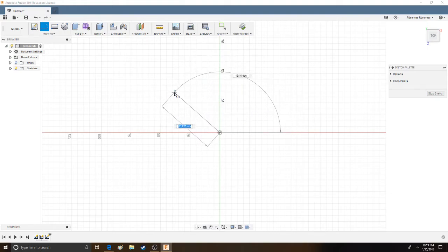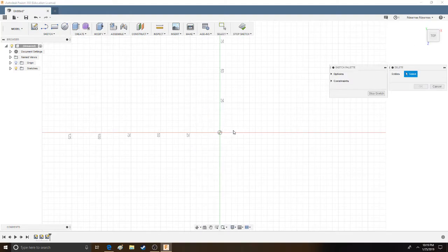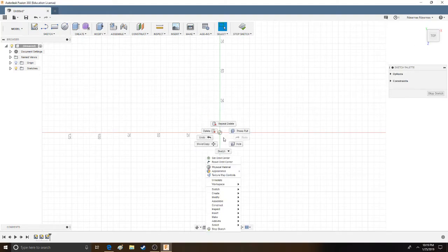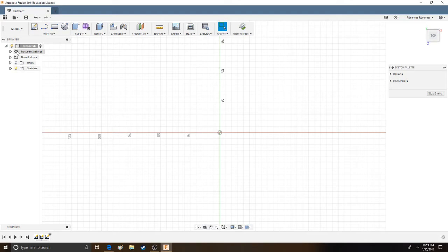So during a sketch, you get this really nice looking grid. So using this grid, we're going to just be going up two sets of 25 millimeters. You can also change if you want. Let me cancel this. Right button click, delete. You can instantly go to that. Right button click has a bunch of different menus, but we will be getting into more of the hotkeys later on. So if you ever want to change the way your document's set up, you can change the listed units to meters, centimeters, inches, or feet. But for now, we're going to be using millimeters as they are the default.